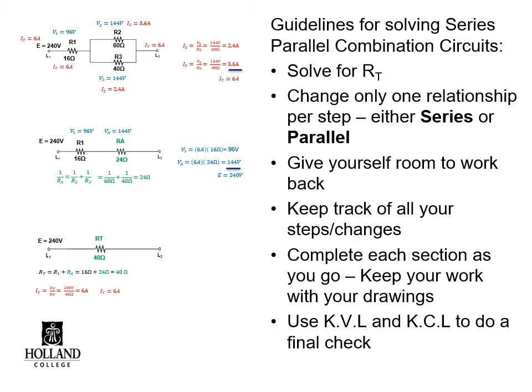You should check your work at each step. And once you're done, you can use Kirchhoff's voltage law or Kirchhoff's current law to do a final check. Even in the most complex circuit, you can use Kirchhoff's voltage law, which says the voltages along any one current path must add up to the source. So if you take one complete current path from start to finish and add up all the voltages, you have to reach back to the source voltage.